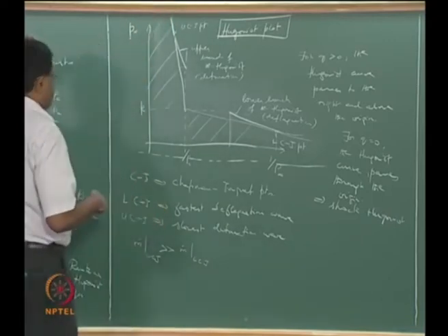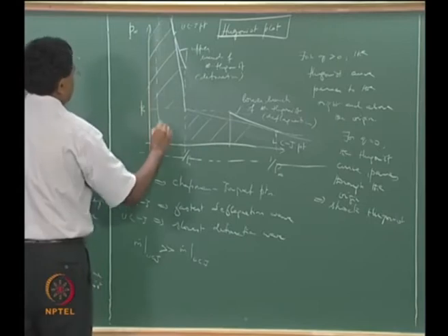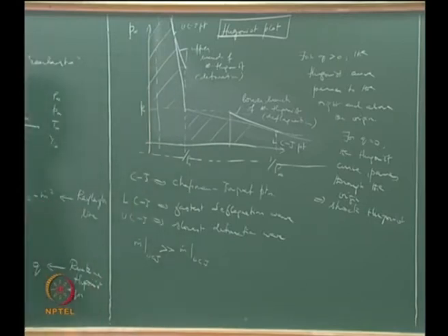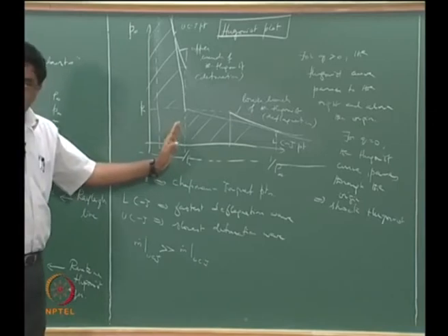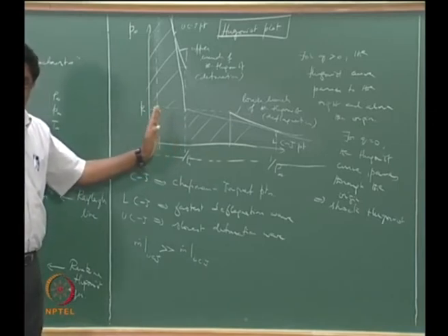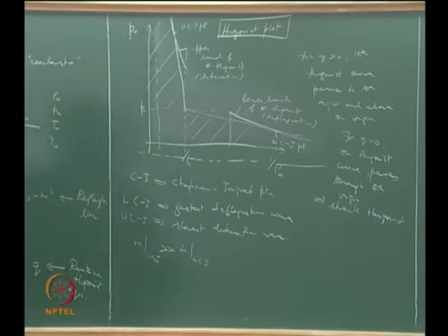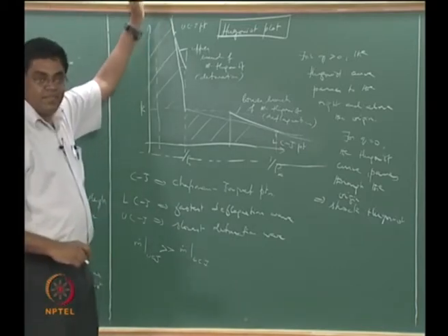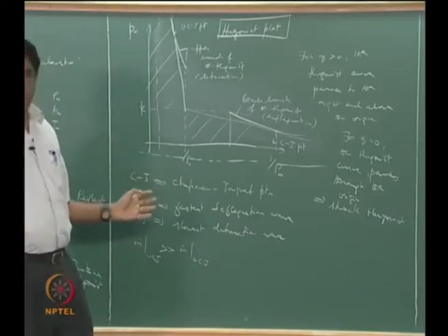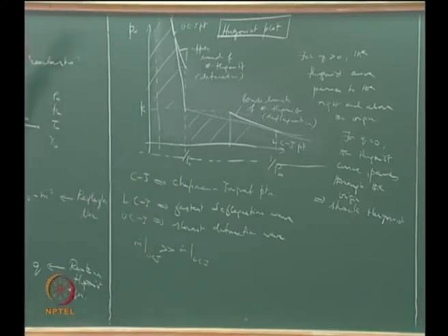So what you will have to find out is there is a vertical asymptote which is having a positive value of 1 over rho infinity, that is the lowest 1 over rho infinity that it can take, but it is now going to asymptote to that, that means the maximum value of P infinity that it can take is infinity when it hits the asymptote eventually at infinity. So these now give you limits for these pressures and densities that it can take in these different branches of the Hugoniot curve.